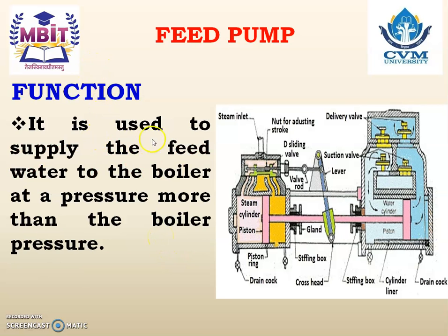Function. It is used to supply the feed water to the boiler at a pressure more than the boiler pressure. So here the function of the feed pump is to increase the pressure of feed water so that it can be entered into the boiler easily, because in the boiler the pressure is high.